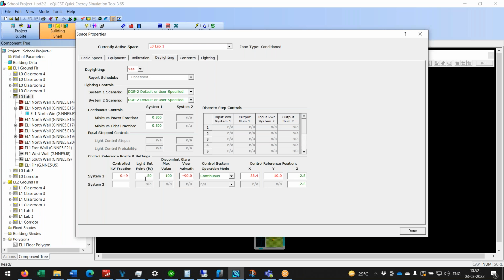Regarding the copy of the ECBC document, I think you can ask the EEV cell. They should be able to share it with you. Yes, dimming has to be coordinated by the sensor exactly, and yes, luminaires also shall be capable of dimming. If the luminaire is not capable of dimming, obviously you can't dim the lights.